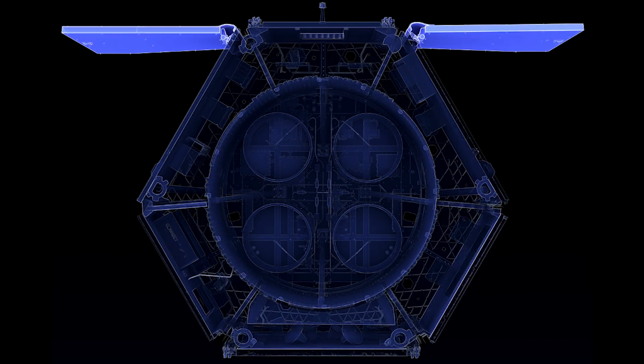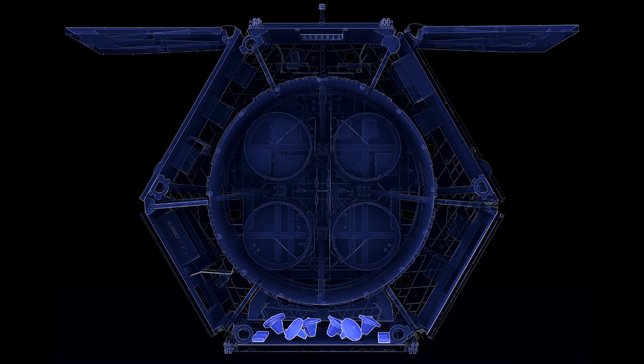Next is the lower instrument sunshade, LIS. It consists of two deployable panels attached to the spacecraft bus, which are designed to help shield the observatory from sunlight. The attitude control system, ACS, is a three-axis stabilized system that uses precision pointing to rotate the observatory to the right position for science. Six motorized flywheels called reaction wheels will enable the observatory to perform short, frequent movements to repoint at different regions of the sky required for science observation.